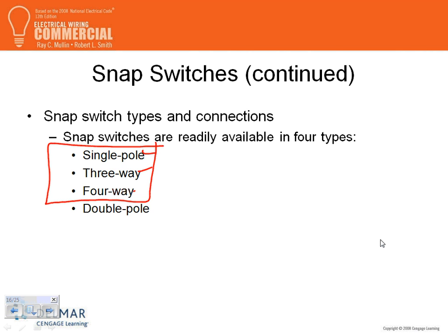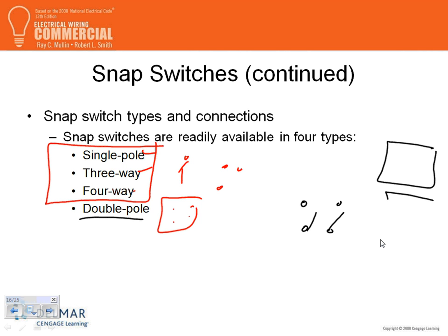But if you want a cheap design, high voltage switches, your options are single pole switch, 2-pole switch, three-way switch, as we said here, or four-way switch. The 2-pole switch, guys, this one, if you want to switch 2 fixtures with 2 hots, here's my terminal here, and I have 1 set of lights, another set of lights over here.